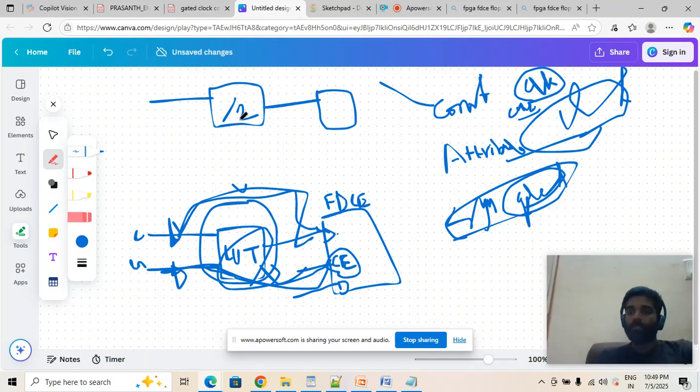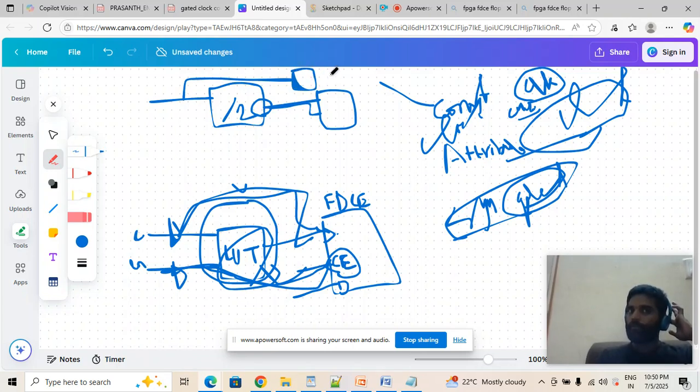We need to write an additional constraint called create_generated_clock, right? So we need two constraints, clock and generated clock. If you apply the clock gating in this environment, this derived clock will go and connect in the clock enable path. We are expecting this clock may connect to one part of the circuit, and this is a real clock, and this clock will drive the other part of the circuit. So we are just applying the clock gating at this derived clock path.